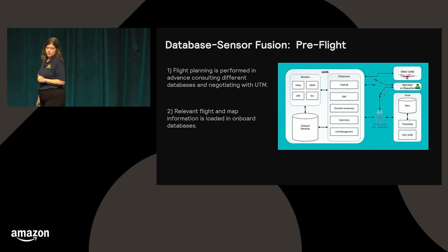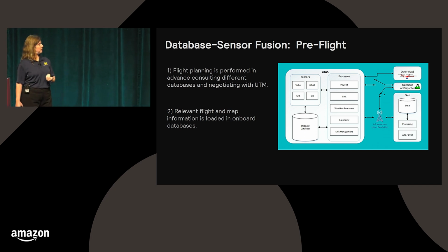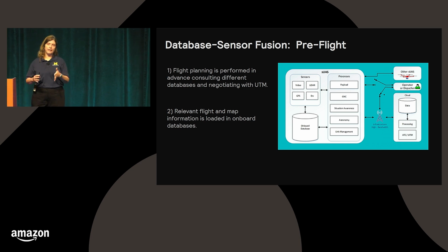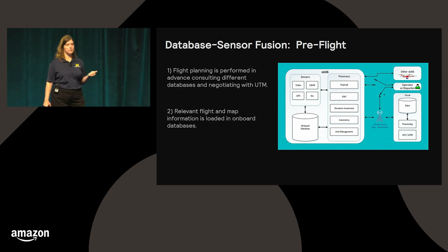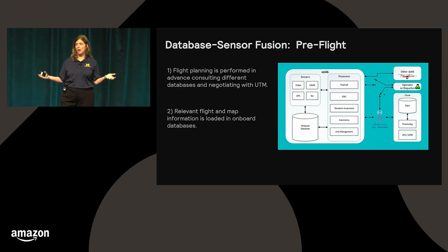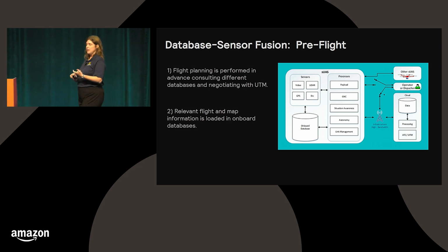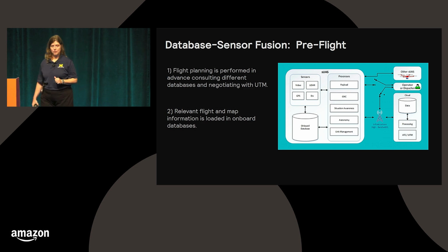This picture also is acknowledging that in the future, we're not going to have line of sight flight where someone with a transmitter is looking up. We're not just going to have really expensive satellite-based communication. We're going to have some combination. Some vehicles already have this, right? So maybe you have 4G going to 5G, you have Wi-Fi, and then you have satellite as a backup. Right? This is desirable. It gives you the kind of redundancy and resiliency that you would need. If one failed, you go to another.